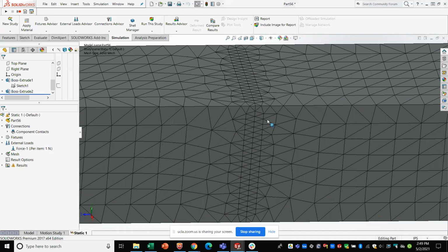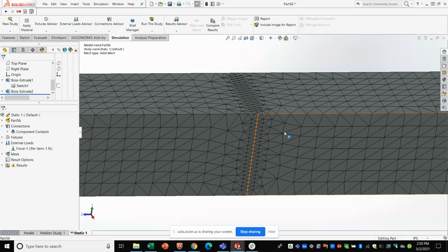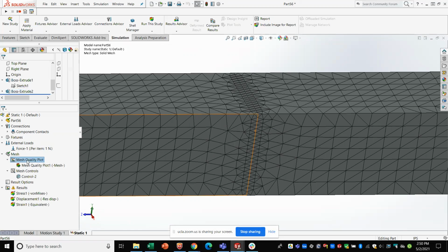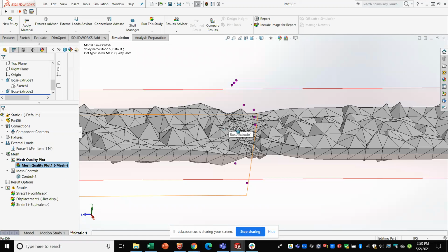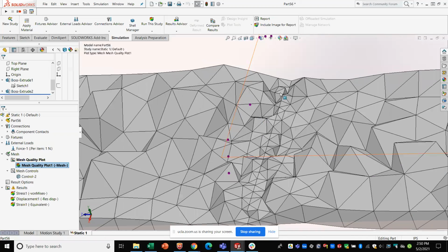It will basically mesh the two surfaces, and it will force them to be treated as one surface. And so even though you applied the mesh quality constraint to one side, it'll get pulled over to the other. And you can verify that by creating a mesh quality plot and then sectioning it. And now you can see that all of these nodes and elements are nicely stitched together.